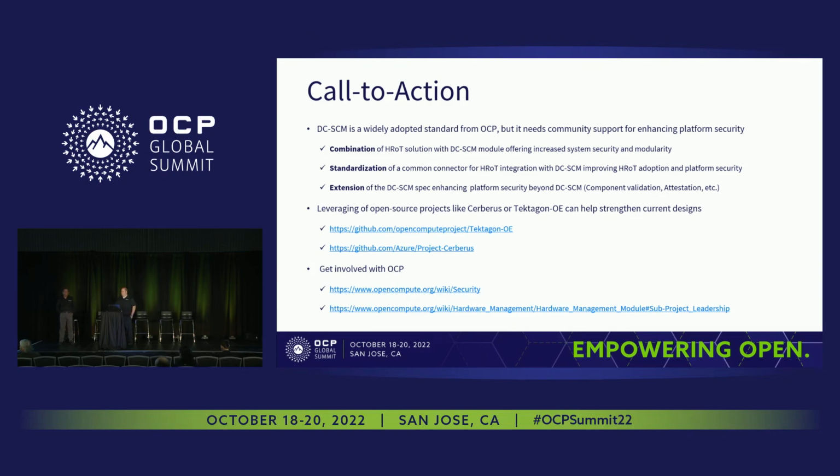Okay, I have one more question, and then we'll wrap up. You talked about DCSCM, and you focus more on that, where the value of the FPGA is as a hardware root of trust. So the threat landscape that you're trying to protect is primarily the BMC, right? Now we talk about some of the I/O and some of the other components on the system. Could you shed a little more insight, let's say specifically for NICs, which have their own secure boot mechanism in some respects? PSUs, you briefly touched on that.